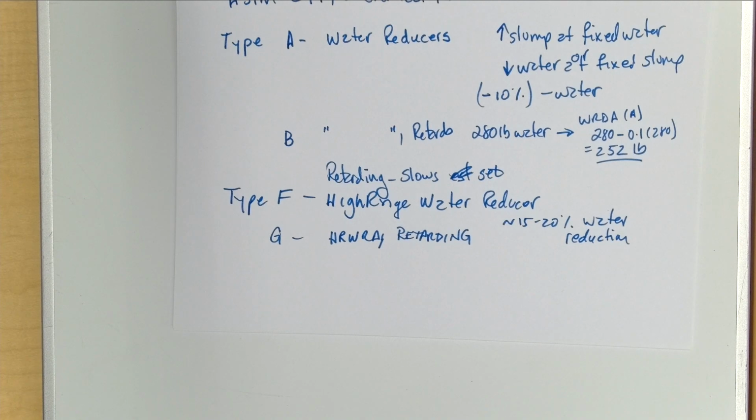There's other admixtures. There's a type S admixture which doesn't have any effect. That means it doesn't deteriorate the properties of the concrete. A good type S admixture might be one that holds the concrete together, makes it less prone to segregation when it's flowing concrete. Types D and E, I can never remember.